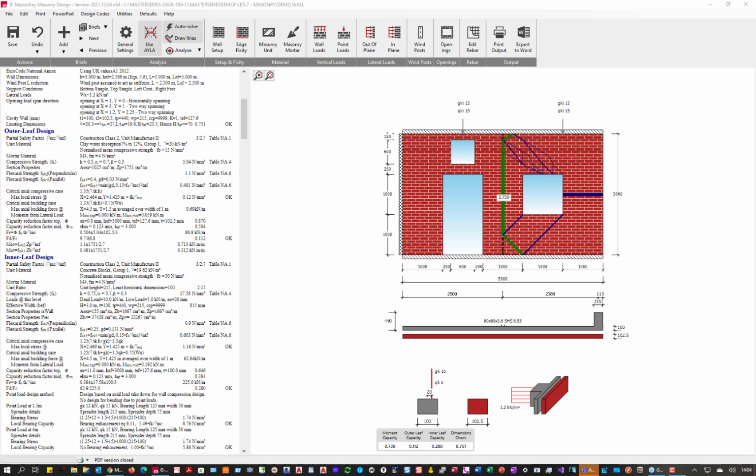What about the top and bottom fixings of the wind post? Absolutely, you're going to have to say, let's take this area of wind onto the post and design our connection for that shear, top and bottom. Absolutely, that still needs to be calculated. The yield line analysis is going to give you an idea of where the load's coming from, but it's not going to allow you to accurately know what the reaction is. The simplest way is to assume half goes that way, half goes that way, unless you want to do an envelope shape and apply it yourself.